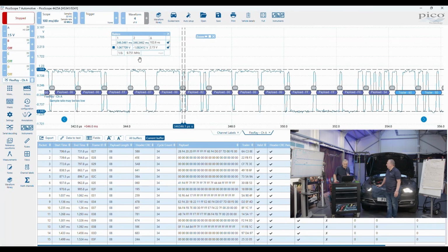It's a valid accessory that gets you out of trouble. You could not do this with a ×1 probe. You couldn't do it with a ×10 probe actually, because we only have the high impedance on one side. So using the diff probe gets you out of jail 100%.